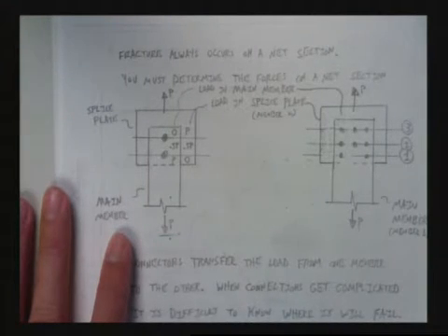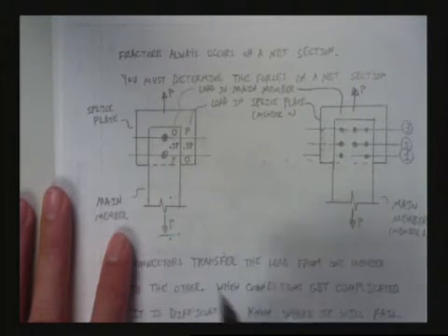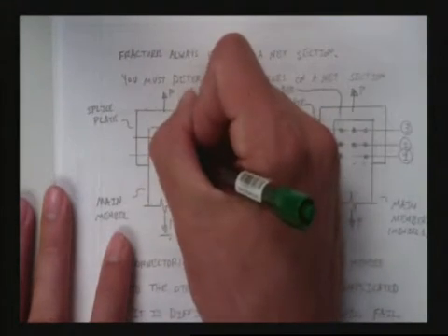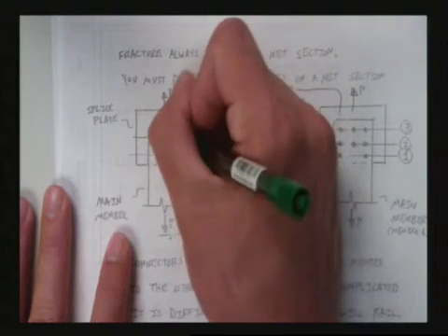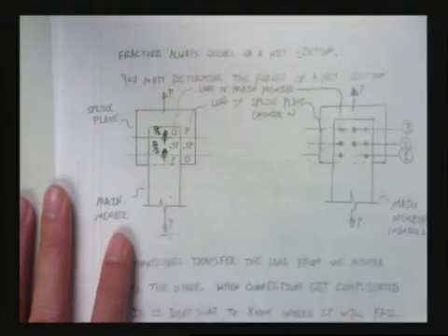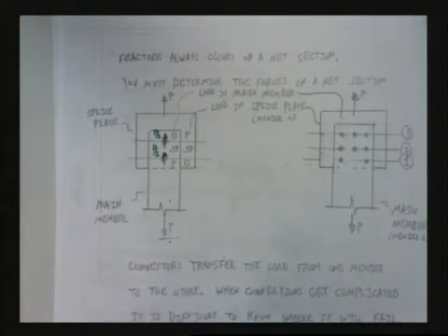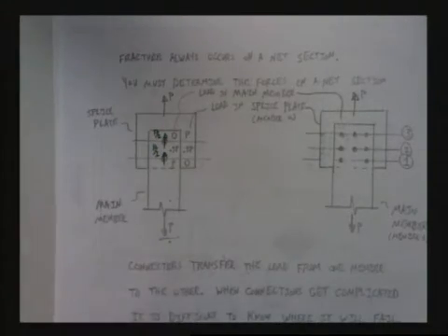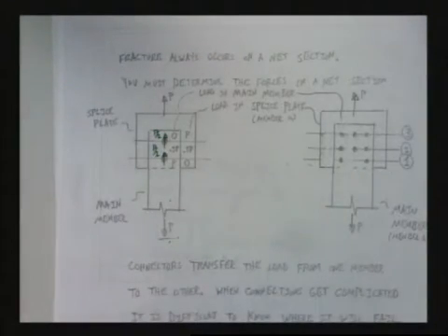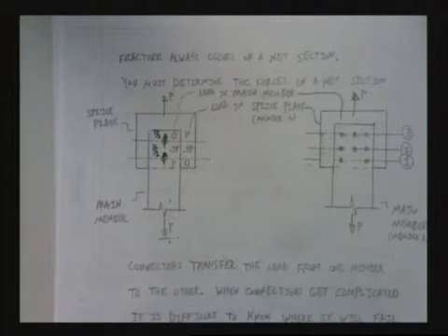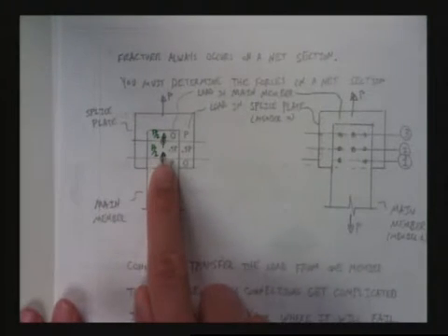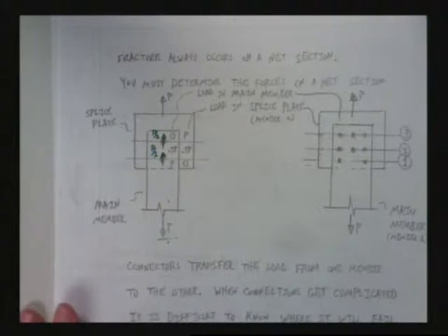Half the load. Well, one could say that they're going to take P over 2 and P over 2, right? Now, if one said that, and they were talking about at failure, they're exactly right. If they're talking about all the points that lead up until failure, it may not be 0.5P and 0.5P. It may be that more load's gone on the one on the front and less load on the back. You with me?